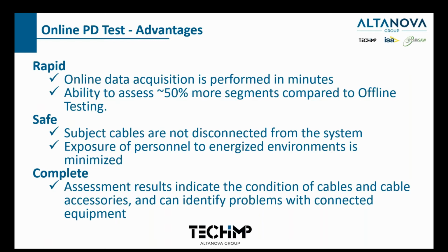Some other advantages of online testing include that the testing efficiency is pretty good compared with offline test, because apparently we don't need to switch off, and we don't need to use an external power supply to do the test. And also, if we're talking about safety, because in online test everything is operating in its normal condition, there's no external power supply, and there's no disconnection. So the operational safety compared with offline test is a plus.